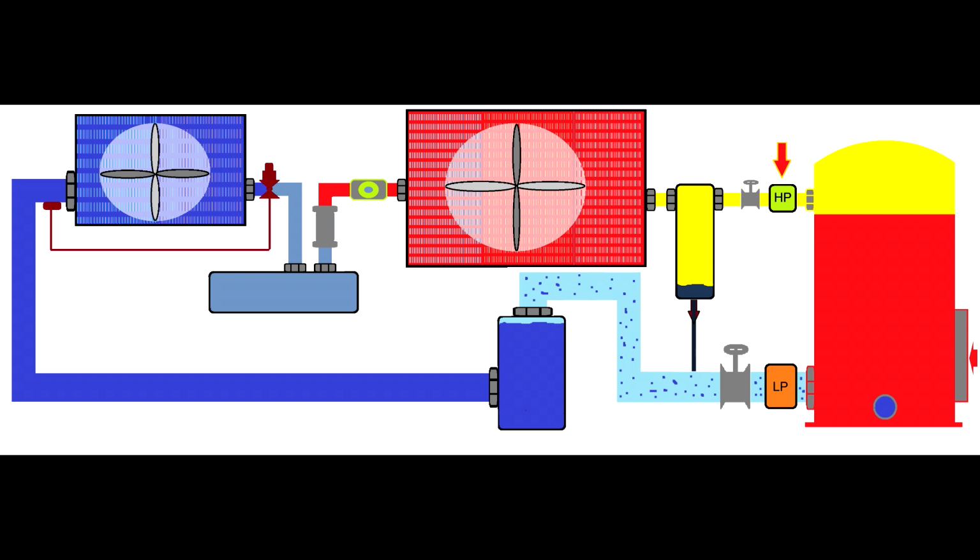As I said, it's not good to put too much refrigerant and overcharge the system, hoping that the system will run better, because you won't be efficient. You need to have a ratio in between suction and discharge, so the refrigerant boils, and if the charge is properly done, it will boil all across the evaporator.